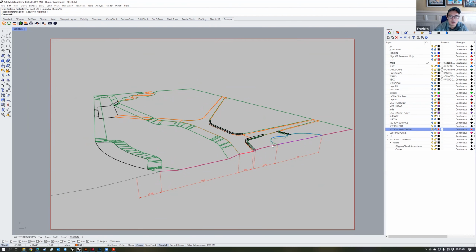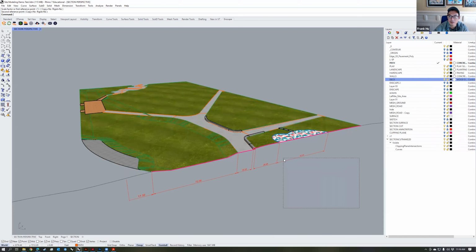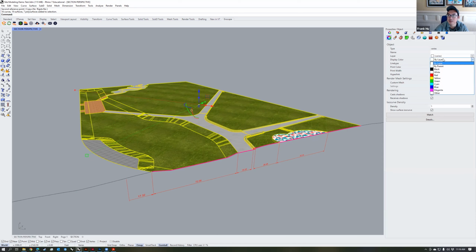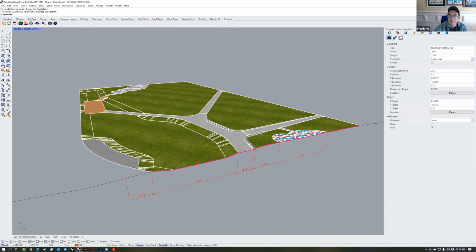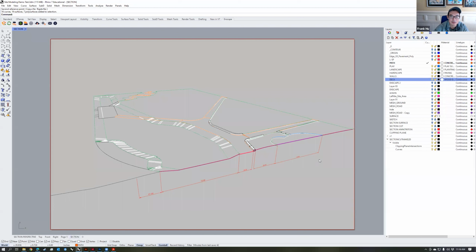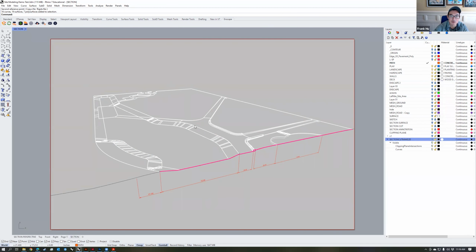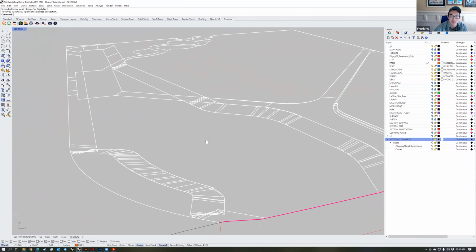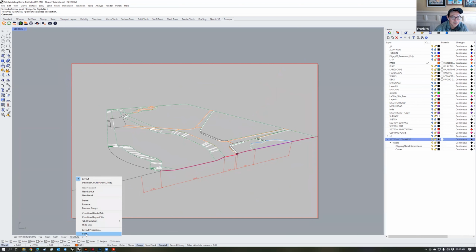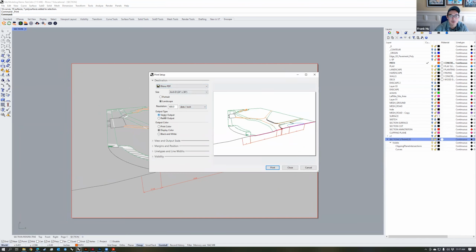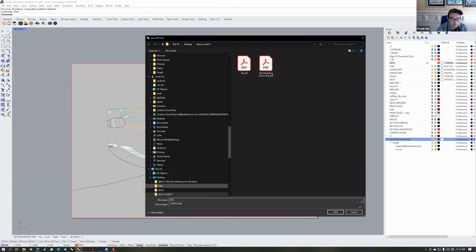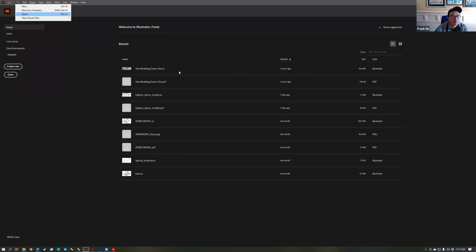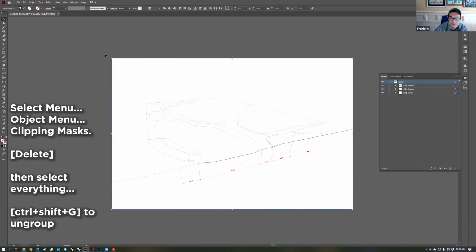So one additional trick that I do is you can select all of the geometry in the model and then go to properties, and then in display color, set that to be like a white color. That way, when you export this out and configure things in Illustrator, you can quickly remove the lines that are from the actual model that have all the UV geometry. Now you take this, print, and then print it as a PDF, vector output, make sure that's checked, and then choose print, section, demo.